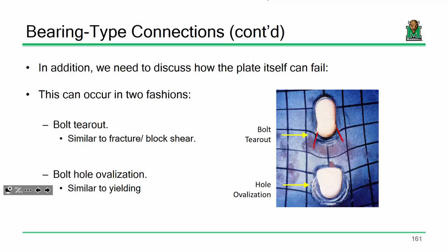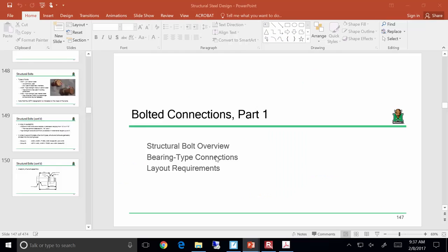Now, here's another question. Remember when we talked about block shear rupture and we got into von Mises? Remember I said there's this number that's going to pop up? Anybody remember what that number is? When we did the block shear path, all the numbers associated with shear had a particular multiplier. It was point something. Not 0.75, a little lower. 0.6. There, 0.6. Let me go back to that real quick.